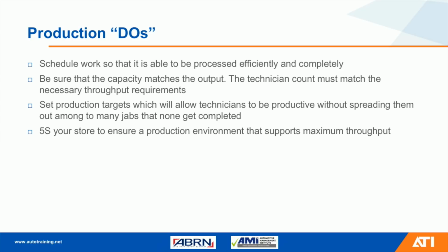Doing things like making sure we're purging the gas. We make sure that the tips are good. Make sure, and on MIGs, making sure that everything is clean. On your spot welders, make sure everything is ready to go so that when the next person grabs that tool to use it and they roll it over, everything's ready to go. That's going to help everyone. So the 5S process is extremely important and something we should always try to do because it helps us maximize throughput.